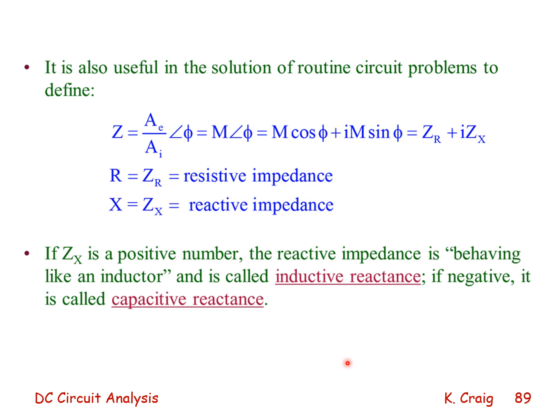When we look at the impedances of electrical and mechanical elements and look at the frequency response, that is by substituting in I or J, which is the imaginary number, times omega for the differential operator, we get an amplitude ratio and a phase angle.